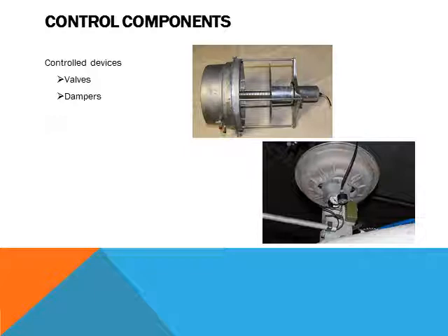The back part of it with the little stem sticking out is the air damper, which moves that long piece where you see where the spring is forward and back to operate and maintain an air pressure in the system. The lower picture is a valve, the large actuator and a pilot positioner on it used to control the flow of a liquid.